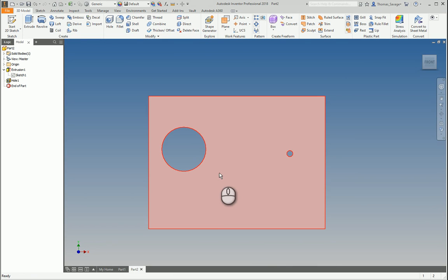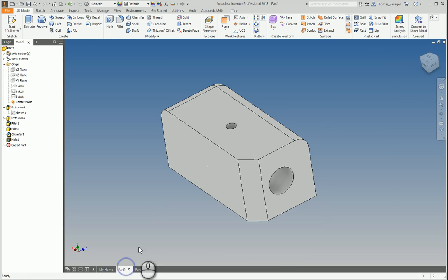So that's the main important things when you start modelling. Always constrain your sketches and keep your sketches as simple as possible, then add the features after. Like I've just shown, cuts or holes, add them after. I think that's about it for the basics. There's a few more in the next video that we can go to.